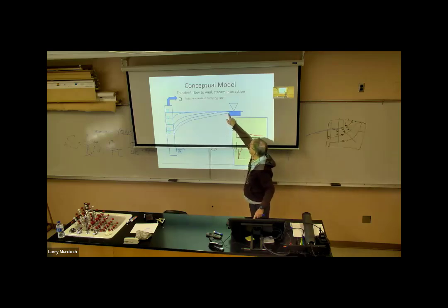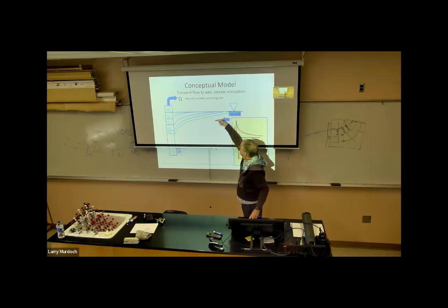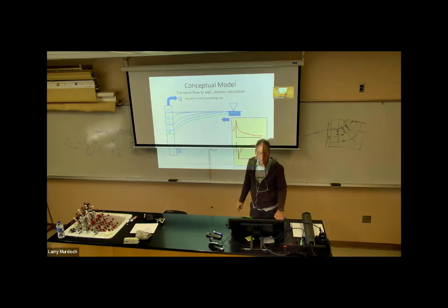So when we go here, this is a constant head boundary. So you can't have this drawdown happen. This is going to cause the head to stay not there, but up here. And this gradient will cause water to flow out of the stream into the aquifer. So instead of producing water from releasing it from storage, you can produce water by taking it out of the stream.